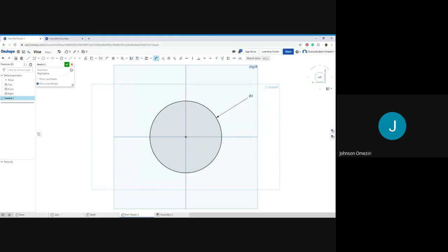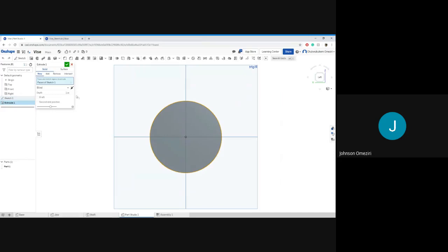So now that we have this, we'll go to the extrude again. I'll press Shift E on the keyboard. Extrude. Now we extrude this by 3 inches. We click extrude after drawing the sketch and setting the dimension. We click extrude, press 3, and click OK.